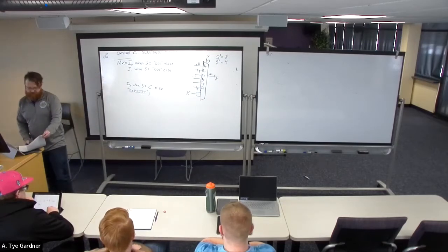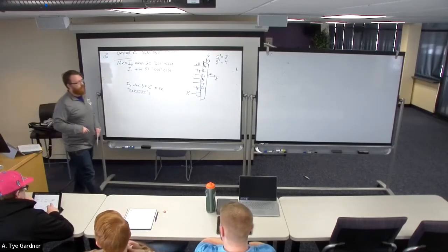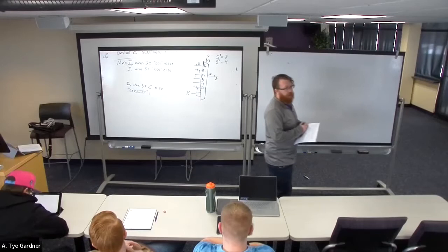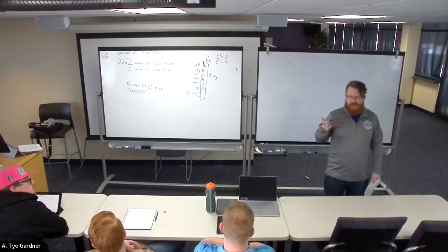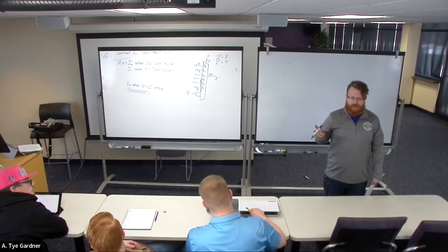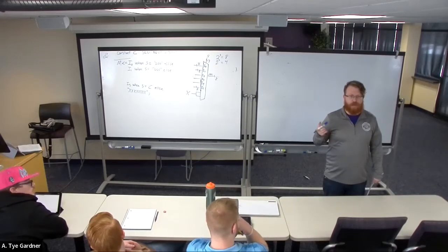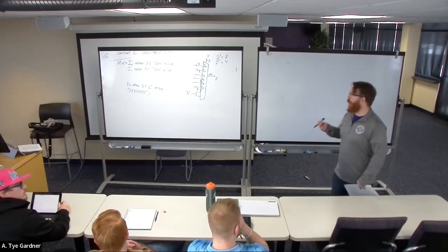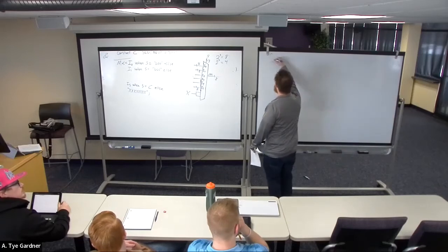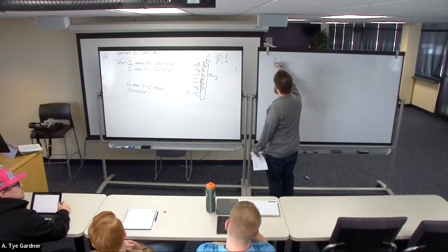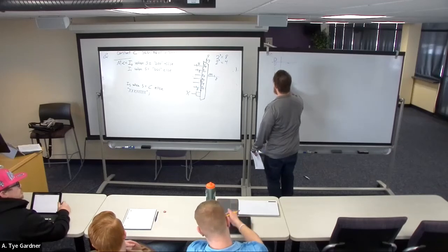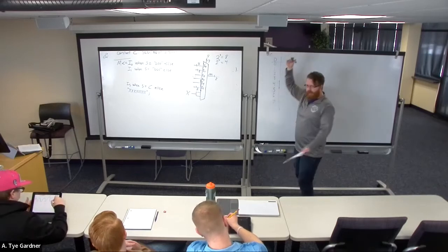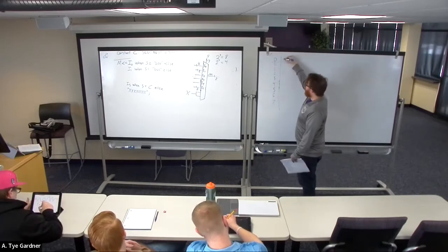Chapter 10 rather wants us to talk about something called encoders. Encoders are used all over the place, and all they do is take inputs and encode them in a different way. How do we want to store that data, right? So let's say that I have something that is a decimal input, 0, 1, 2, 3, 4, 5, 6, 7 is fine. And I want to encode it as binary.